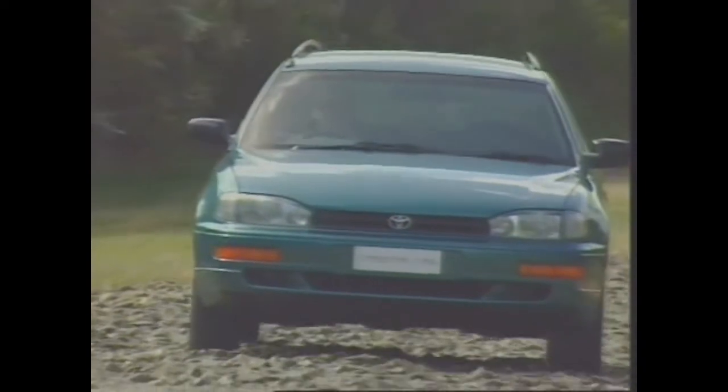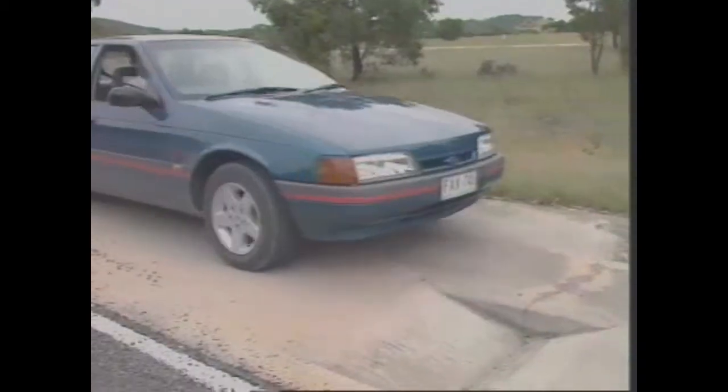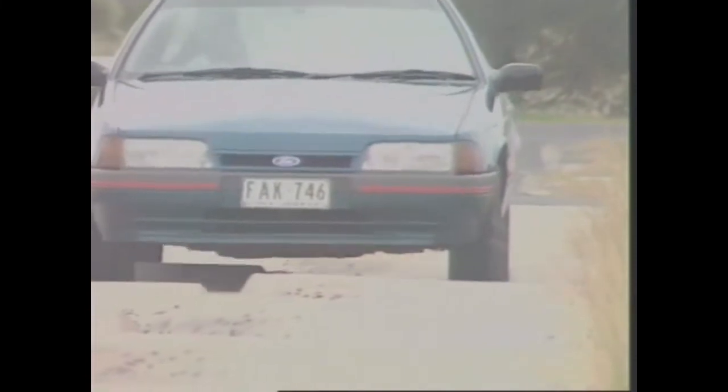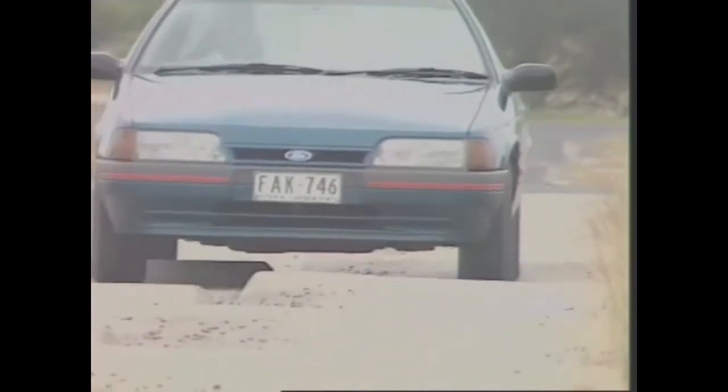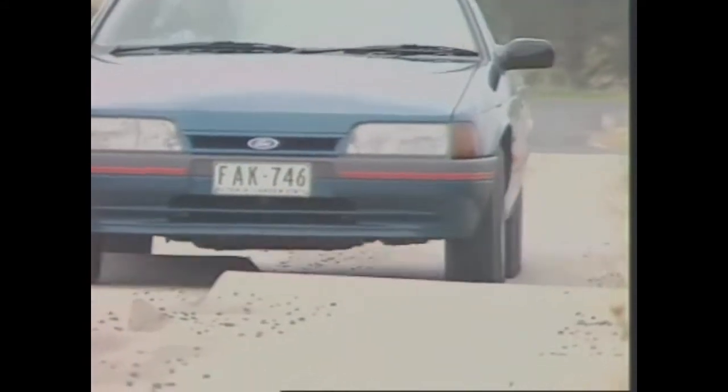When a tyre hits an obstruction, there is a reaction force. The size of this reaction force depends on the unsprung mass at each wheel assembly. The sprung mass is that part of the vehicle supported by the springs, such as the body, the frame, the engine, and associated parts. Unsprung mass includes the components that follow the road contours, such as wheels, tyres, brake assemblies, and any part of the steering and suspension not supported by the springs.